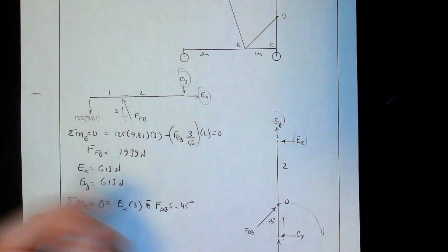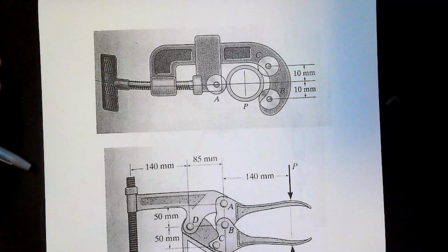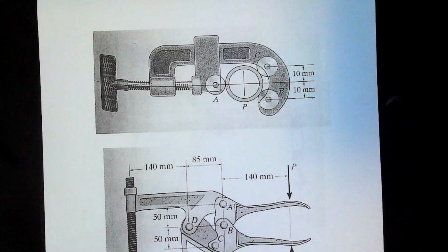It's got to be coming down. And we know the orientation relative to E, it is 1 foot up, the angle there being 60 degrees. And then the distance from here to there to line up with this, that's 1/4 of a foot. So we're ready to go. So we can sum the moments at E, which must be 0.